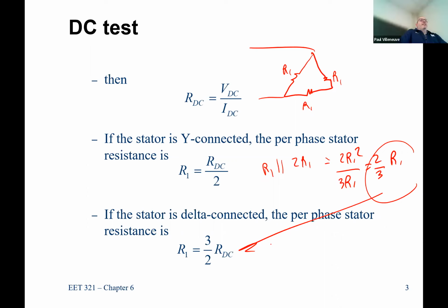Literally, you could go to Reliance and order a 50 horsepower motor, and unless the supply chain issues are still a problem, you could get one in a couple days. 50, 100, maybe 200 horsepower, maybe 250. Once you start pushing 250, your voltages start to change, and those aren't something you can just find locally. Those get to be a little more custom, where you would have more detail.